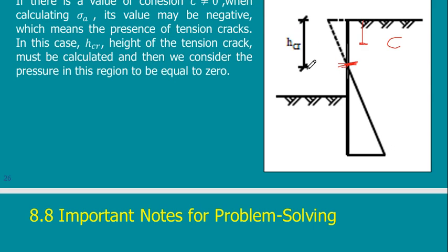So it is very important to have this critical H, H critical, which is the end of the crack or the separation that will happen between the soil and the wall, and this is the shape of the soil once it retreats back away from the wall. Starting from this, I will have my pressure here. In the other direction, I will still have the passive. My passive will be standing here as it is, but my active will start from this point, not from this point.